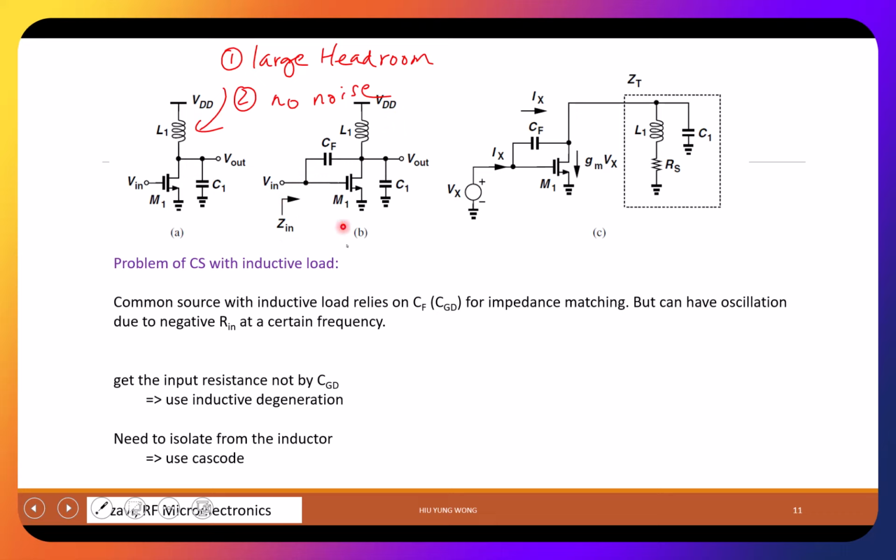So if you try to adjust the input impedance, or later you decided, oh, I'm wrong about L1 because I now realize that, let's say, my L1 parasitic capacitor is too large, I want to further increase L1. And once you increase it, then you need to redesign the Cin, right? So it's just like what he said, iteratively, right?